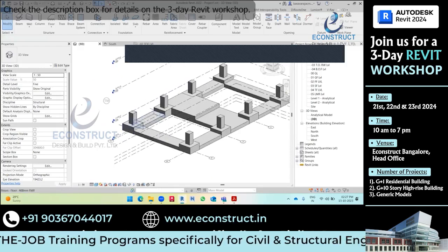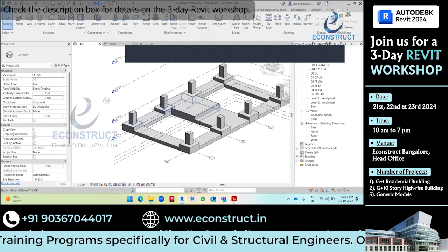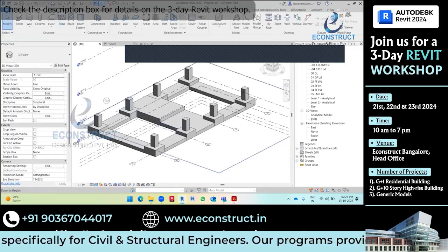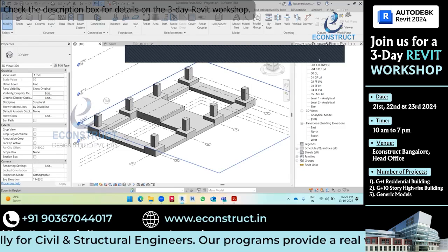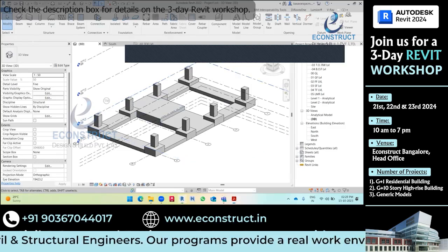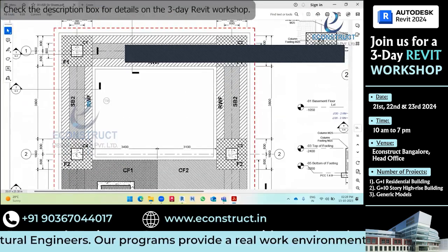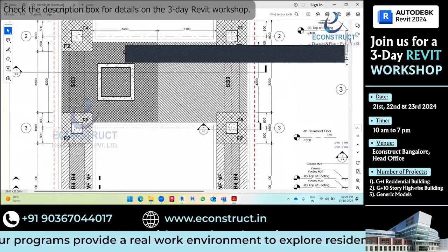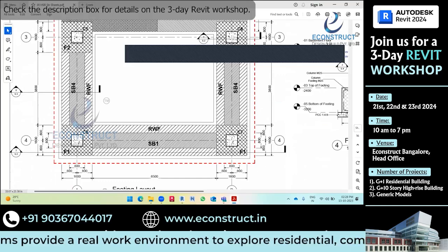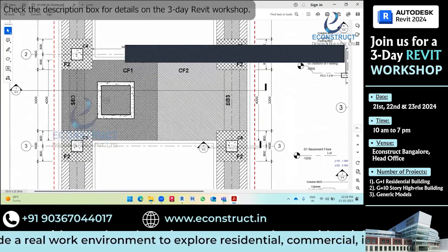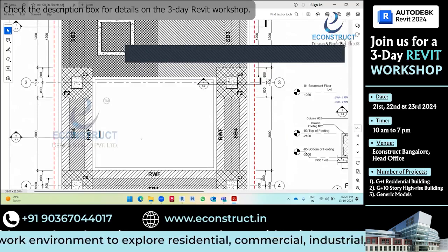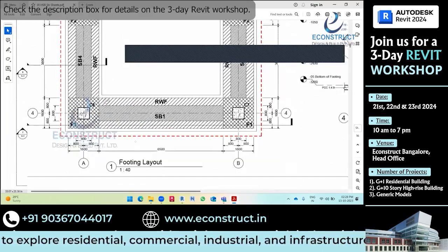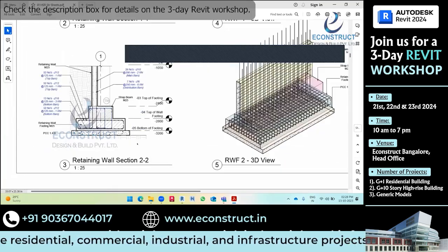Okay, now we need to draw the strap beams. So again go to the top of the footing level, because you can see here this strap beam is there, no? SB1, SB2, SB2, and SB4, SB4, and SB1, and SB3. These are all the strap beams. The dimension of that strap beam is given in the strap beam details.